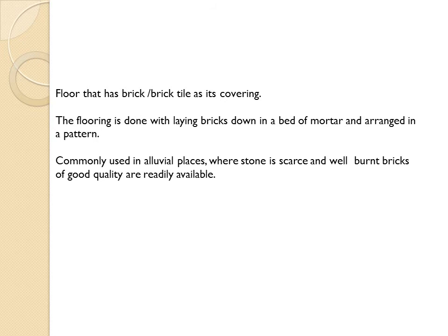Understanding what brick flooring is: the floor is completely covered with brick, which is a building material. The flooring is done by laying bricks down in a bed of mortar and arranged in a pattern, commonly used in alluvial soil places where stone is scarce and well-burnt bricks of good quality are readily available.